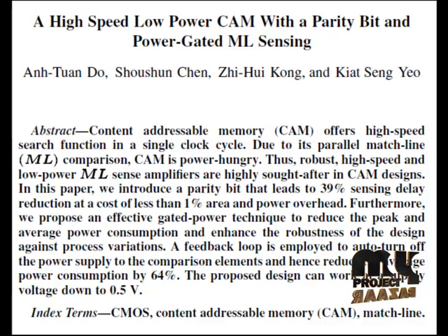For example, consider a CAM consisting of 4 words with each word containing 3 bits arranged horizontally. There is a match line corresponding to each word feeding into a match line sensing amplifier, and there is a differential search line pair corresponding to each bit of the search word. A CAM search operation begins with loading the search data word into the search data register, followed by pre-charging all match lines high, putting them all temporarily in the match state.